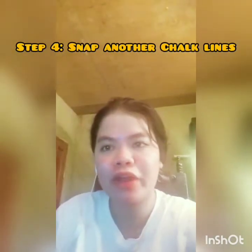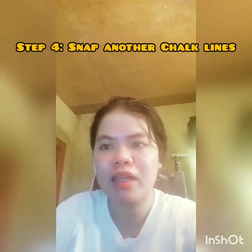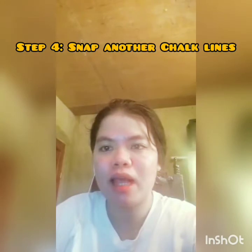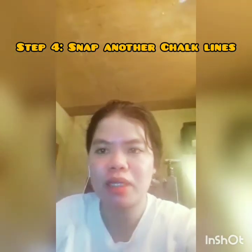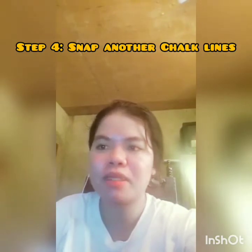4. Snap another chalk line. Snap an additional chalk line with the width of a tile out from each wall. This will help keep the tile placement perfectly straight. Continue laying out tiles and spacers until placement is correct.